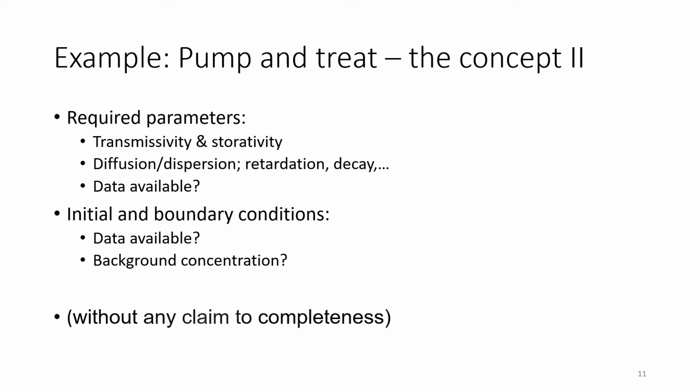And the same is true for the initial and boundary conditions, right? So here I had my groundwater model, but as I said, there were no wells in the middle. So assuming a homogeneous subsurface is just my best guess based on the data I have. But maybe my results will show I can't explain the experimental findings in the field with a homogeneous model. So maybe I want to do some geophysics or more drilling, more in-depth analysis of the subsurface to see if there are some underground structures which are inhibiting flow or changing hydraulic parameters of my aquifer in some way, right?